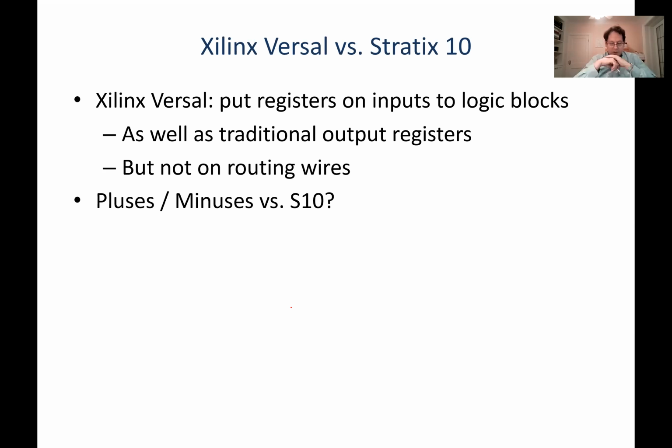Okay, so Xilinx Versal also is a bit different. Xilinx's earlier chips have all the registers in the logic blocks in the ways that we've seen so far. You basically put the registers after your logic. You have a lookup table and you have a register. So that's inside your logic block.